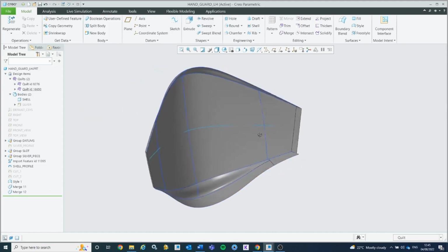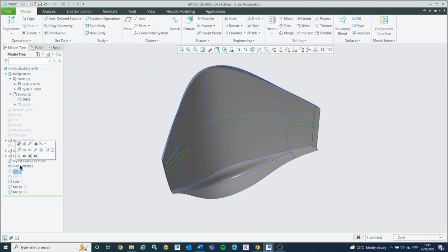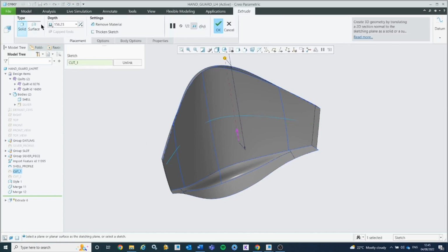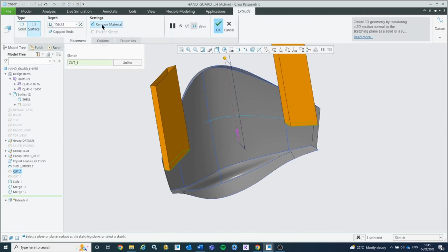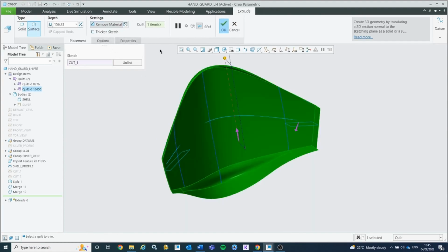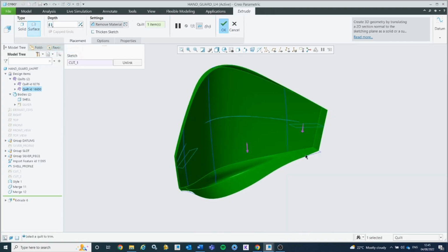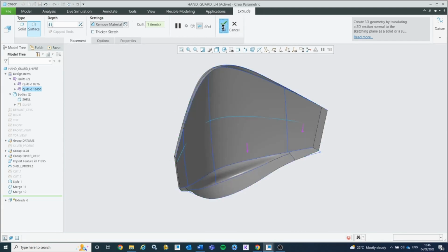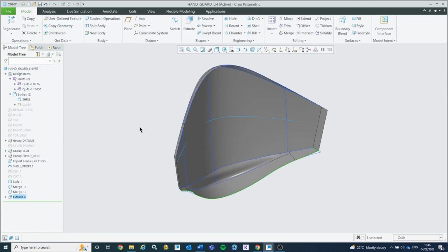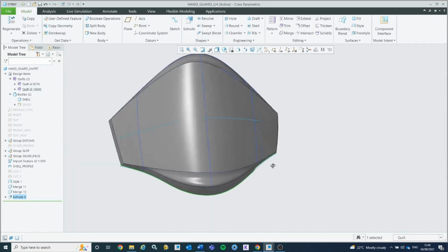So first of all, what I'll do is use a cutout here of an extrude, and use that to remove material for when it comes to putting it together on the actual motorbike handlebar assembly. So we'll just go through all, and we're removing these little sections on here so there's no interfering parts when we assemble everything together. So we can hit OK, and then we can move on to the next section.